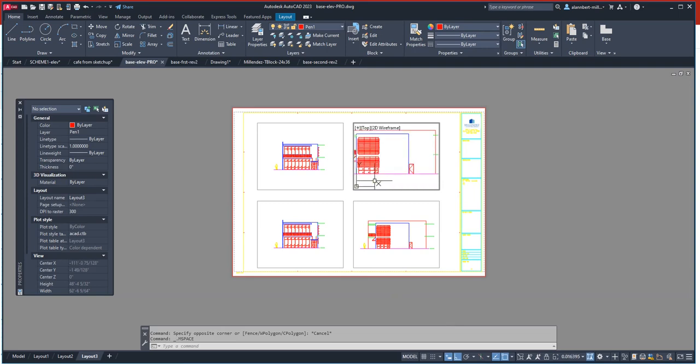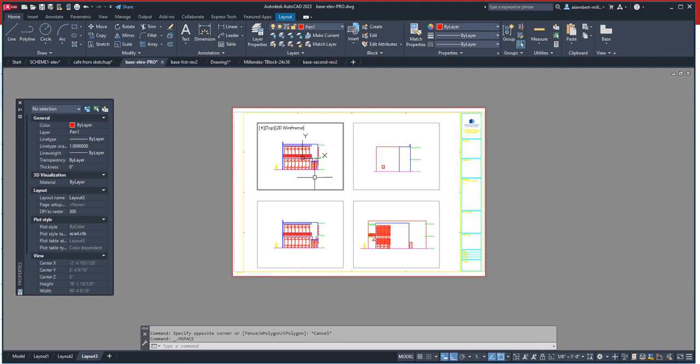So the rear elevation, oh, is this one. That's the rear elevation, and we wanted to show... Oh, I made a mistake. So we wanted this one to be the rear elevation. Rear elevation. There you go. So that we can show the elevation here on this side. Let's go ahead and set the scale on that one to 1/8 equals a foot. Okay, and then just lock it.